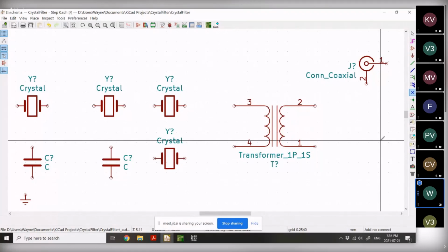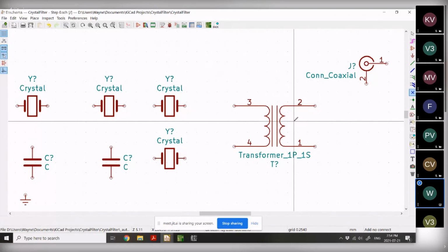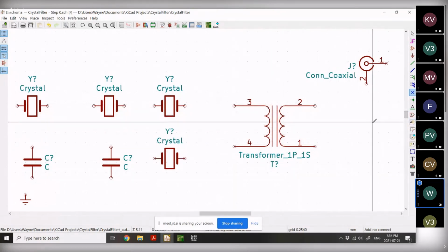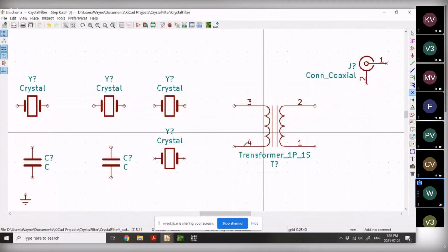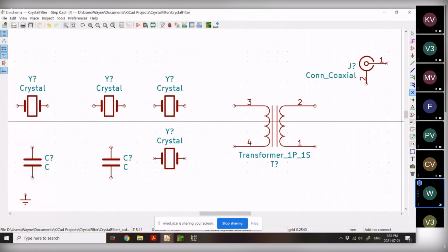And then you use the features on the right-hand side to name the wires which should be appearing as the parts that appear in the subdiagram on this thing. So a subdiagram will appear as kind of like a box with lines coming out of it. Those are the wires that you want to show on the parent diagram. So your microcontroller disappears into a box, and you have a few wires coming out, and you have the power and ground going in and that sort of stuff. Okay, that's what it's for.